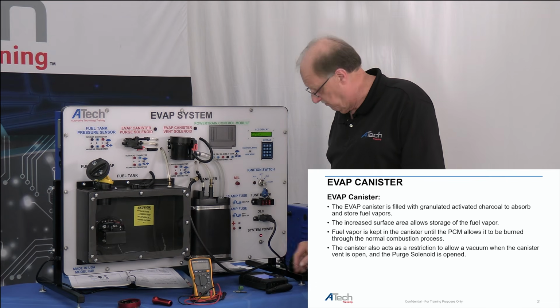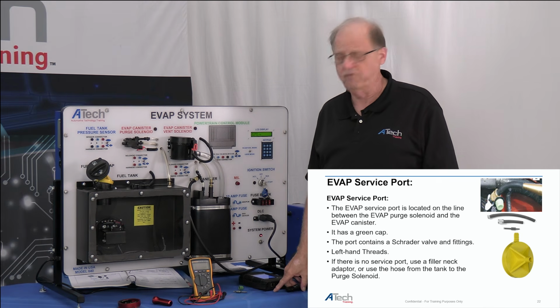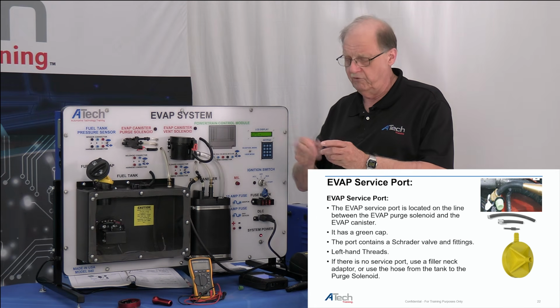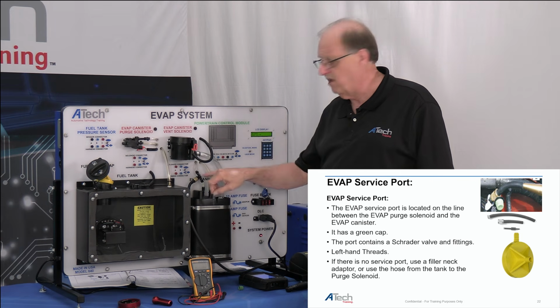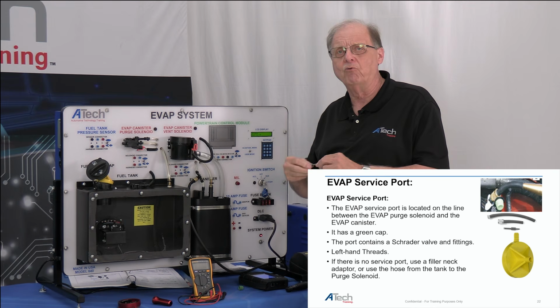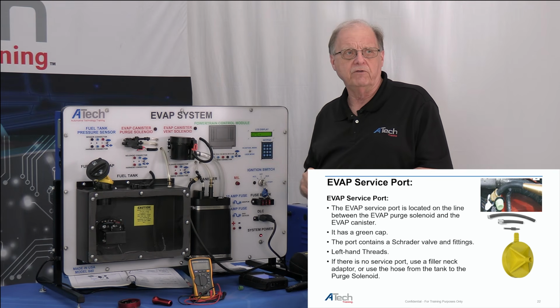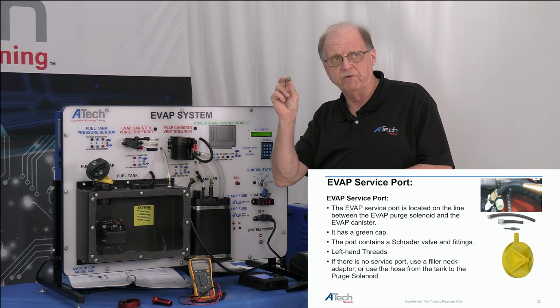When in reality something in the canister vent will cause you an issue. Now, as we go forward on this system, we look at our service port. Again, you've already heard me tell you that not all cars have it. The service port's up here. You're going to have a little tool, and this little tool up here is a little bit longer. It's a left-hand thread up there. You want to pull that out when you're servicing this. You also want to put it back in correctly and not damage it. I've seen a lot of guys damage the Schrader valve in there. Now, it normally has that green cap that we're looking at. I showed you a little bit before.